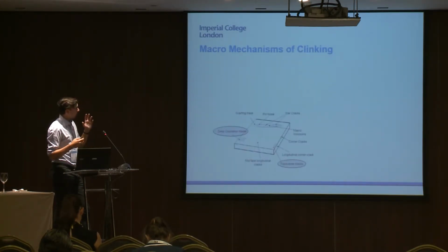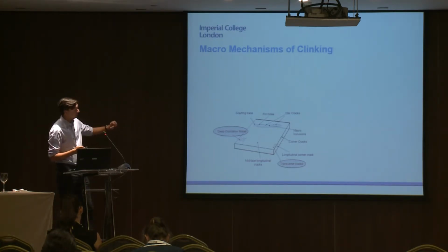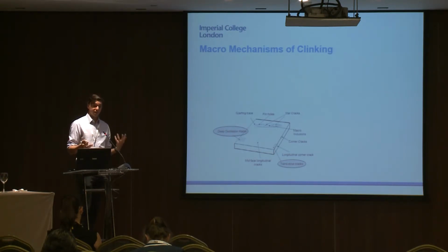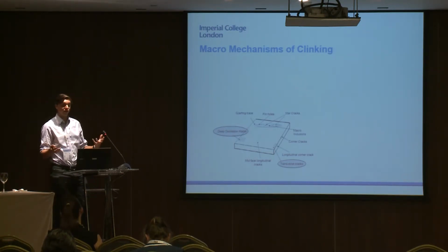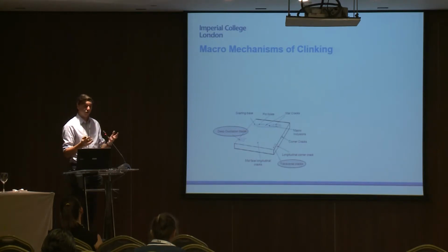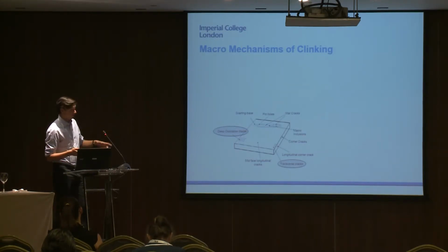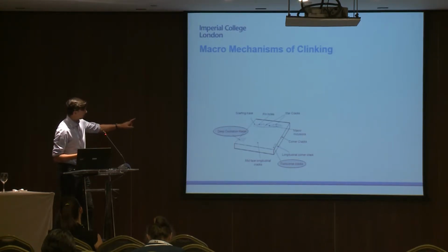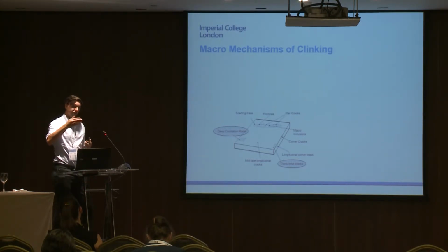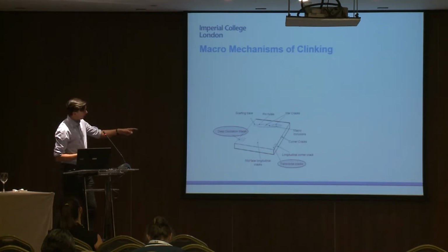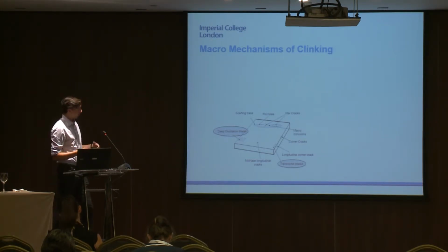So what I'm going to talk about now is possibly our thinking about how these cracks start. This diagram here on the bottom is a typical diagram of a lot of casting defects that you might have. It's well known within the casting industry that you can form a lot of defects. The ones that we're particularly interested in for this problem are these deep oscillation marks, which are dents in the surface that form when it's being continuously cast, and also transverse cracks. The reason we're interested in these is because we know that transverse cracking, as I'll explain in a little bit, is a function of the composition, but also these defects are in the same orientation that we see the cracks happen.